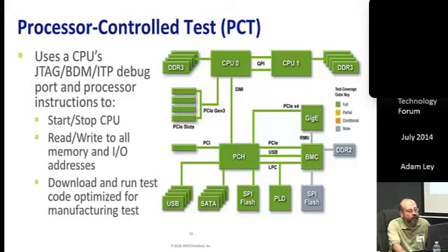And by doing so, you access the interconnects, test the interconnects, and you also access interface function and a certain amount of function that's in those chips. You basically keep going progressively, extend your sphere of influence, starting at the core of the processor, moving out gradually until you've run test code that lights the entire diagram up in green.